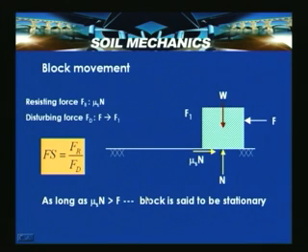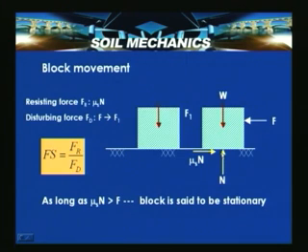Now, this resembles something analogous to the block movement we studied in engineering mechanics. Here, as long as this force is less than mu Sn, the block will be stable. So, consider a block of weight W, and its normal reaction is N. Now, once this block is subjected to a force F1 greater than F, it will be subjected to a movement and it will continue to move. The moment this F crosses this mu Sn, the block will move in the direction of the force. The similar analogy happens when the slope portion moves on a certain surface.